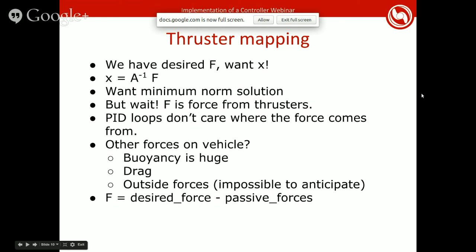The way this is applied practically, one of the biggest benefits, at least for CAV, was roll control and pitch control. If you're trying to maintain zero roll, and you're slightly rolled one way, you might say, okay, I'm too high on one side. So the PID loop is going to say, I need to output a torque, an angular acceleration, that's going to roll me back down to 0.